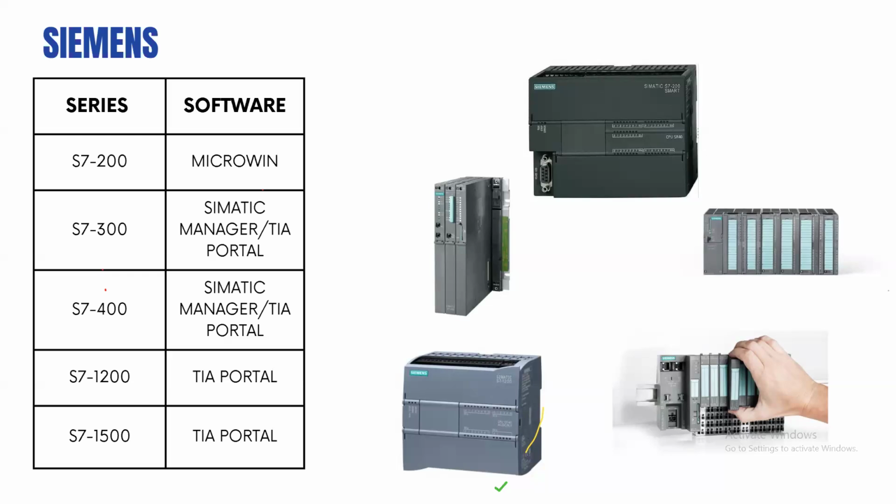They don't care about having beautiful graphics. They don't care about all this. They just want to start. So you can just have a VFD that can run independently. You use push buttons to control it, and then your status signals can just go back to your indicator lamp or something like that. And for your potentiometer, you can just use your hand to adjust the signal. And then there will be a display on the VFD to know the speed that it's actually running at.